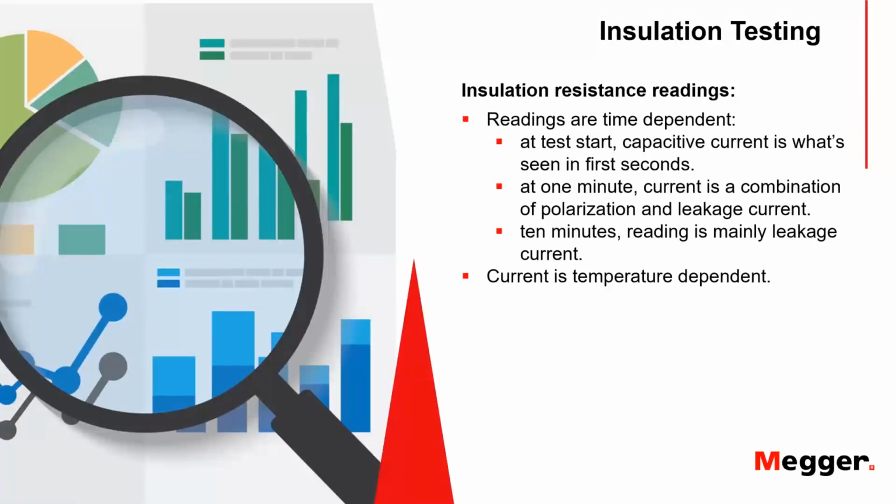And two big factors: insulation testing is time dependent, and it's also temperature dependent. Keep that in mind, and we're going to come back to that time and again. Those are variables that you need to take into consideration when you're doing an insulation test, and especially when you're keeping records or when you're reporting the results to a third party.